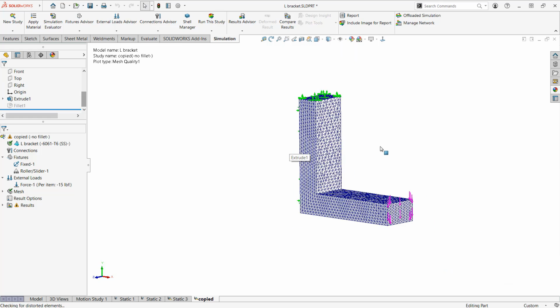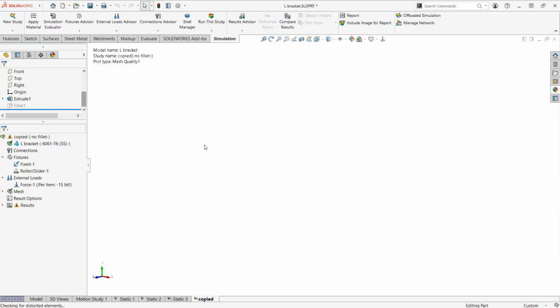How does it know where to put a big element and where to put a small element? Well, that has to do with an actual quantity of the element that we call the aspect ratio, okay? That goes to the quality of it. Now, it's an actual quantity. It's something we can quantify. We can say yes or no if an element's good based on a particular number.